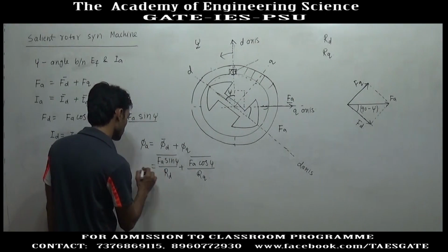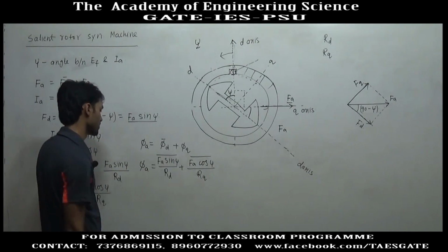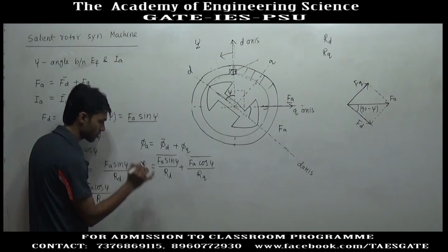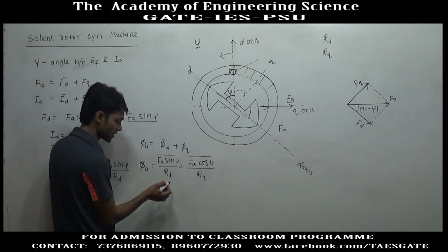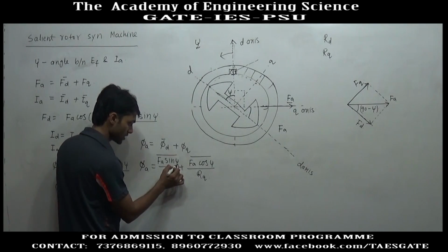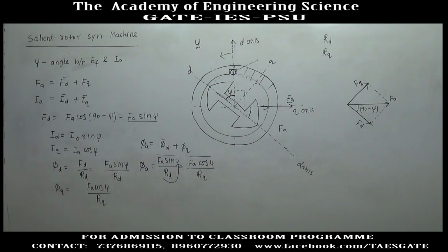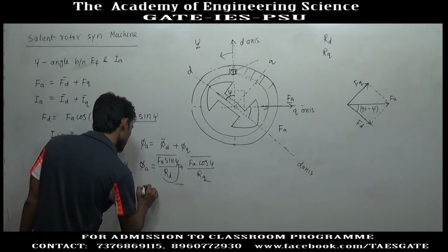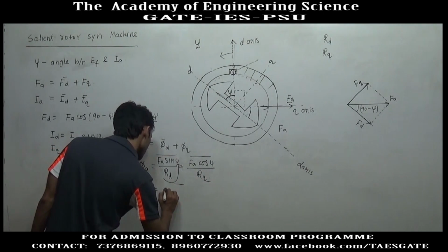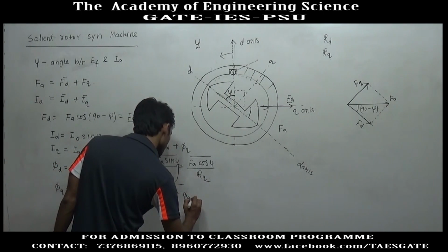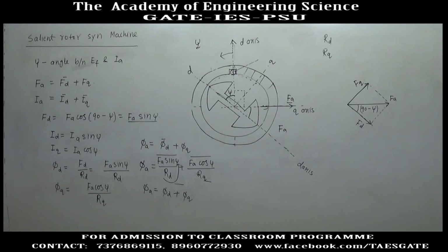So we will take the vector sum of these two quantities and we will get the total armature flux. And this will depend on the power factor of the load. The effect of power factor angle has already been incorporated in psi angle. So we will not use this relation, we will just say the armature flux is equal to D axis armature flux plus Q axis armature flux.